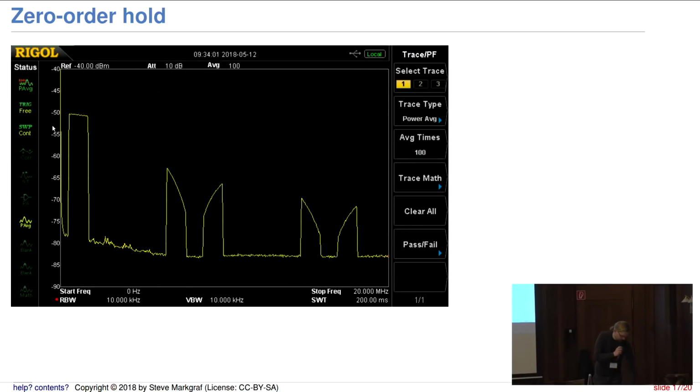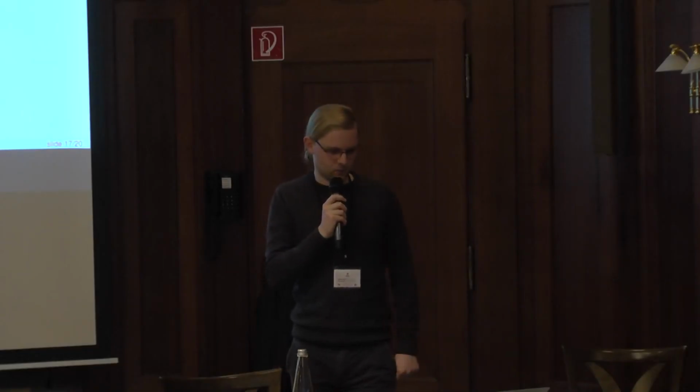I think he also added a filter. Yeah, but it's around 0 dBm, a bit less. But you actually can combine the DAC channels, of course, for more output power. So they are matched to 75 ohms, but you just can send the same data. You of course then need to take into account the delay of the traces and so on. But yeah, it works.